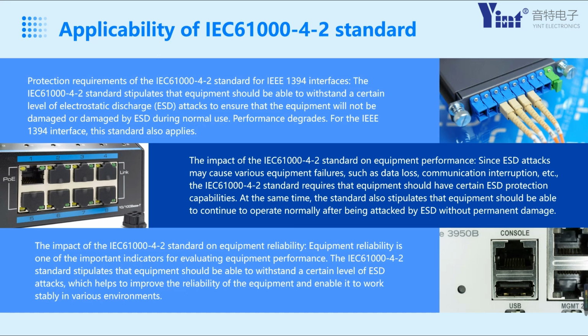Since ESD attacks may cause various equipment failures, such as data loss, communication interruption, etc., the IEC 61000-4-2 standard requires that equipment should have certain ESD protection capabilities. At the same time, the standard also stipulates that equipment should be able to continue to operate normally after being attacked by ESD without permanent damage.